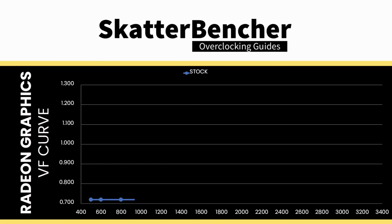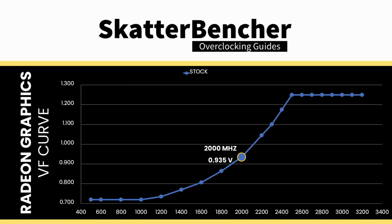Here's the default voltage frequency curve of the Radeon Graphics. We can immediately make a simple and redundant observation. The higher the frequency, the higher the voltage. For example, for 2 GHz we only need 0.935 volt, but for 2.5 GHz we need 1.25 volt.